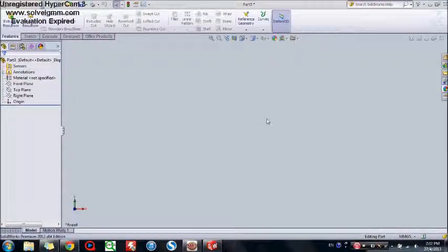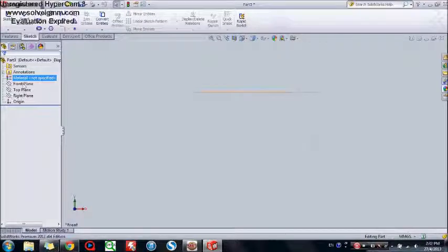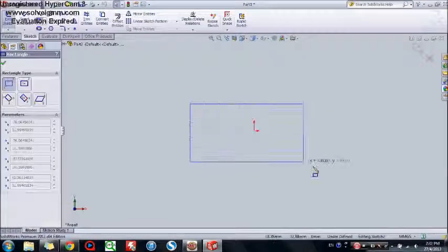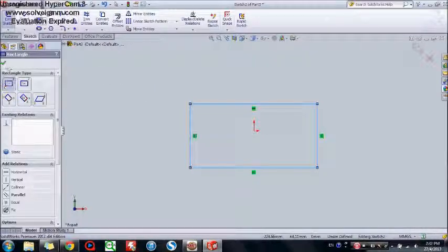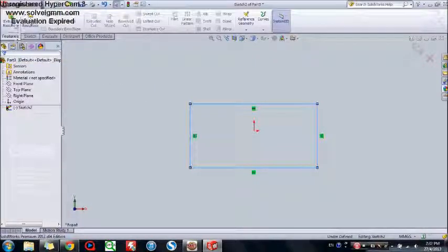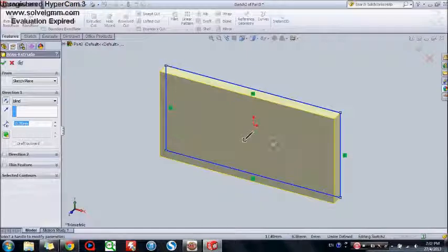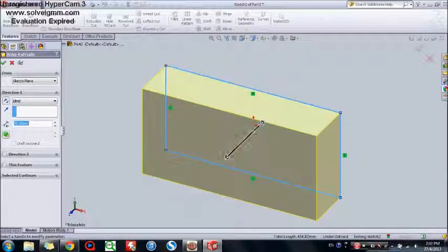Today, I'm going to teach you all how to extrude boss/base. Firstly, choose any shape that you like, such as a triangle. Then go to Features, Extrude. You can choose the length that you want or determine it over here, like what I chose, 40.